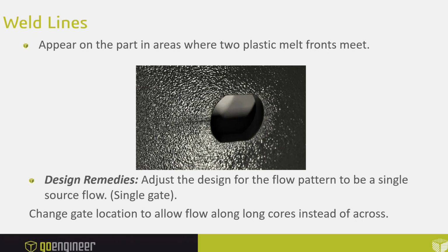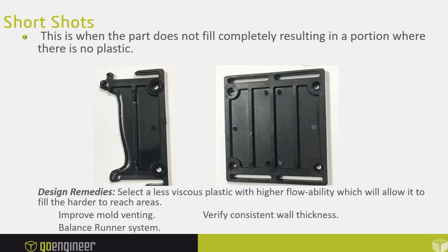But beyond that, that same sort of concept applies to plastic. So when the plastic flows around a pole or an opening and then it meets back up, you get all this jumbled, disassociated, not completely mixed flow fronts that are at slightly different temperatures that then cause these micro dislocations or micro cracks in the design, which is essentially either one, visually not satisfying, and two, structurally weakened in that location. Short shots is another great one for plastics, right?